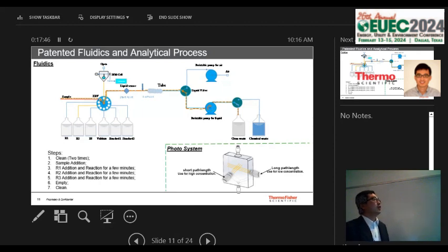Similarly, we do it for the reagent. We're sampling, for example, 0.2 or 0.1 milliliter of reagent. We use a smart sensor again together with a section of tubing to determine how much we're sampling. This way we improve the accuracy of sampling volume down to 0.1%. If you're using a pump, the sampling accuracy can be 5%, sometimes 10%. So that's a major issue for your measurement inaccuracy.